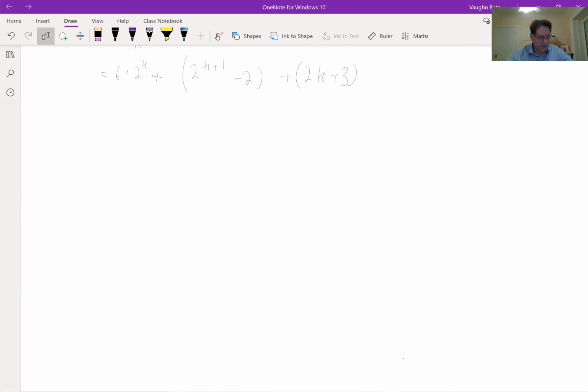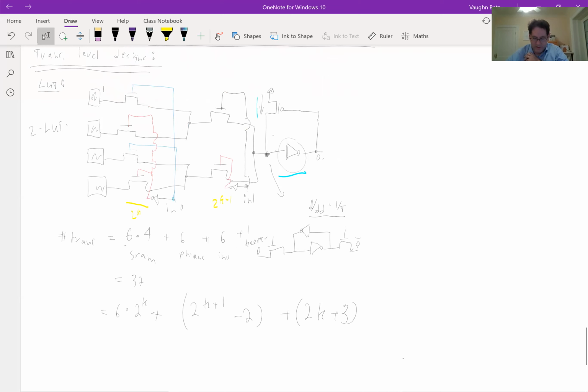This is just counting transistors. And I said we really shouldn't just count transistors. We should try to estimate their area. So some of these transistors are going to be bigger than others. The transistors in the SRAM are generally very small. Okay, so the SRAM does not have to be fast. We're going to write it when we configure the device, and then we're just constantly reading it. It never changes. So we can make all these transistors quite small.